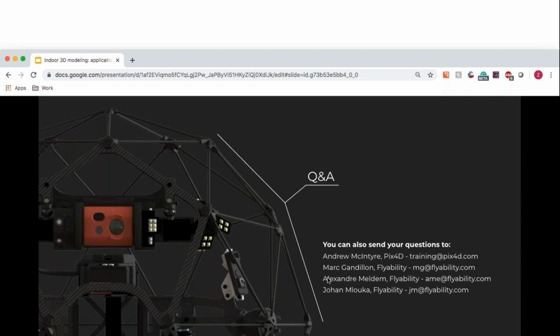I think it does, unless Marc, do you have anything that you'd like to add? Just to add some information on the order of magnitude that the Helios 2 is able to achieve: when you're at 30 centimeters from a surface that you're inspecting, you get a resolution of 0.18 millimeter per pixel, which is the ground sampling distance, basically. So this is the most precise degree at which you can capture data, but definitely there's no way you can get that kind of accuracy on a very, very large model like the one we've presented today.